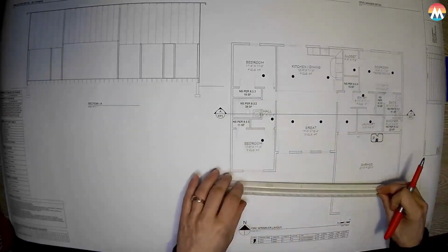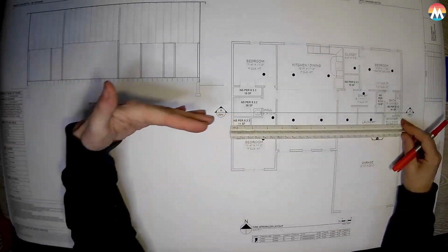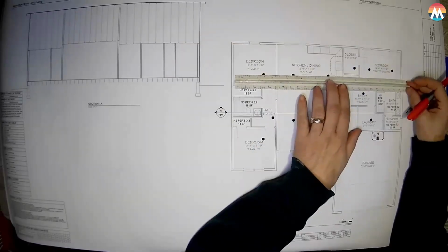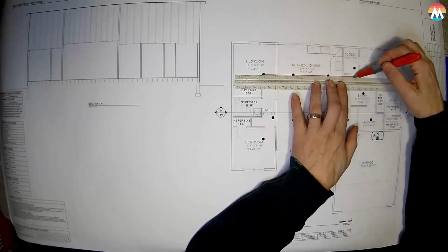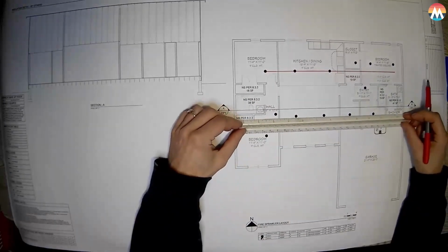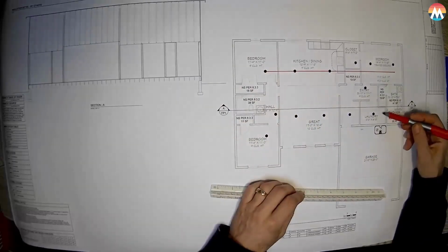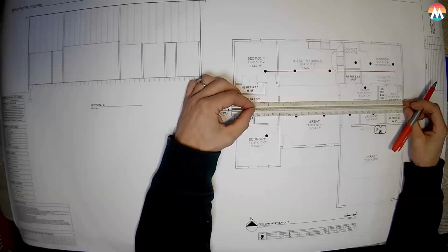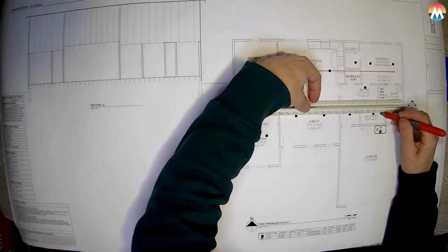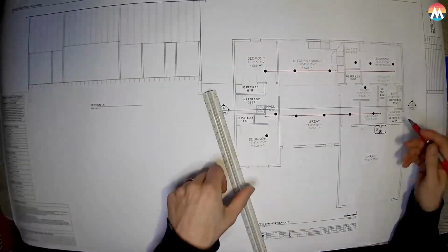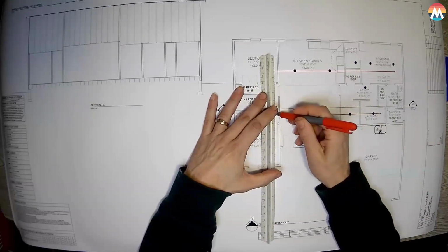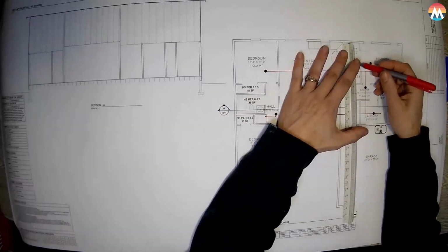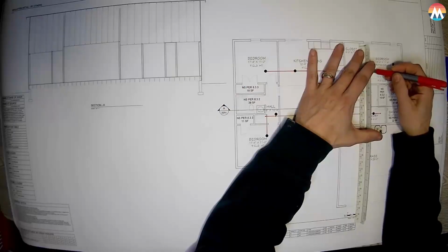And what that's going to translate to here is we're going to predominantly be running this direction as much as possible. So I'm just going to start by drawing some lines in that direction. And let's see. This tank and pump is going to feed the system from the riser right here. There's going to be a vertical pipe rising up. So my line is not perfectly straight, but you get the idea. We'll connect these two going through this sprinkler in this entryway, and then we'll run a couple tail pieces up to these. I guess there's more than a couple, there's 3.